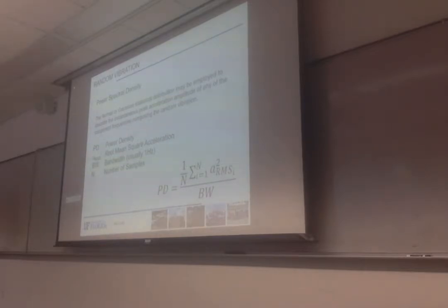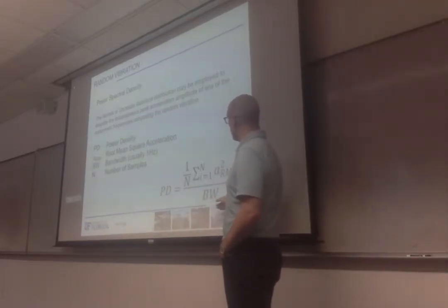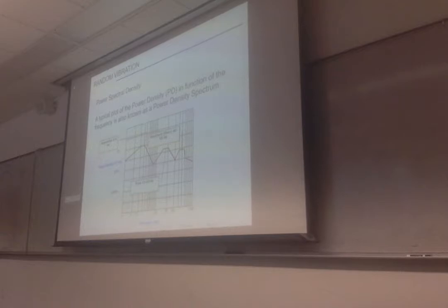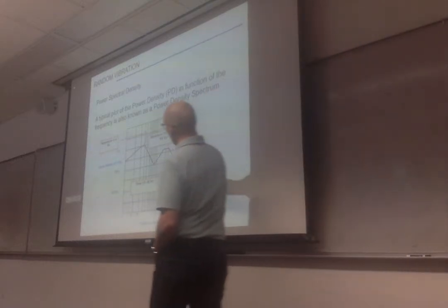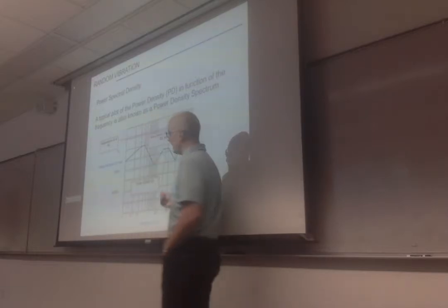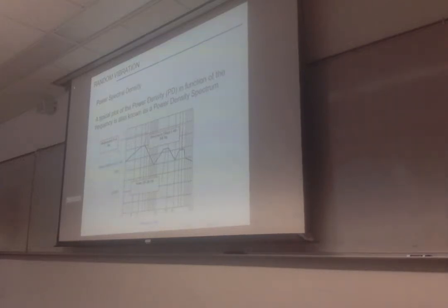So in here, in that equation, the bandwidth is typically usually 1 hertz. So this kind of goes away right away. So the power spectral density, okay, looks like something like this. I guess you guys were not very curious on Monday, but if you were to look at the screen I was working on in the lab, this is what you will typically see, okay? You will see a graph that will look something like this, okay, with different profile depending if you are going to be working with truck vibration, radio vibration or air vibration.